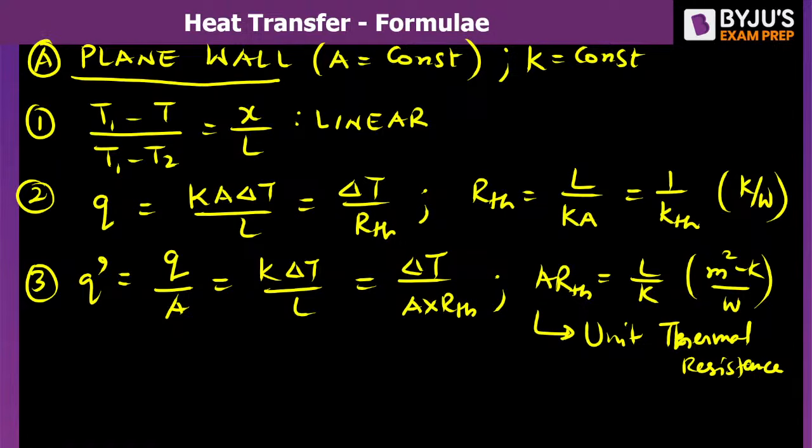It is not watt per Kelvin, Surendra. It is Kelvin per unit watt. Look here: delta T has unit Kelvin, and we divide by Q. R_TH is equal to delta T by Q.